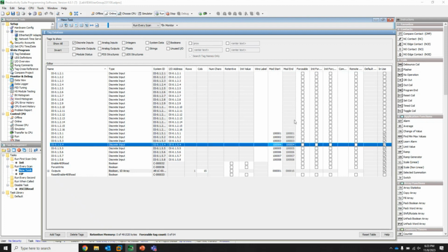One of the catches on some of these is if you have gaps. So like here, in this application, I'm programming both the PLC and the LabVIEW application. It's much nicer in Modbus. You can read up to 250 data elements at one time, one go. It's a lot more efficient than doing 250 reads. But if there is a gap in your data, you can end up getting an exception for an illegal address because nothing exists there. So I just deleted my discrete input number 4.